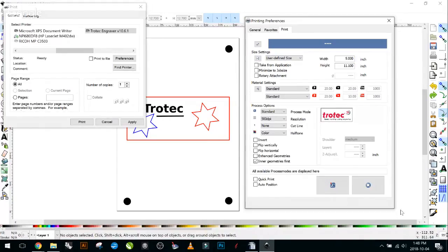So of course, if we were to cut this star out first, that would not be a problem. The star would fall, our square here would still have to be cut out, and we can go ahead and cut out that square afterwards. So to make a long story short, use the inner geometries. It's always good practice. Of course, unless you have an application where maybe this doesn't make sense for you, but I have yet to see where it does not make sense.